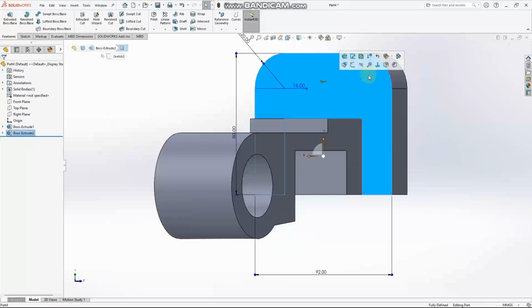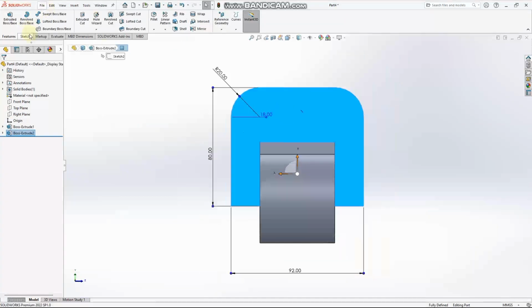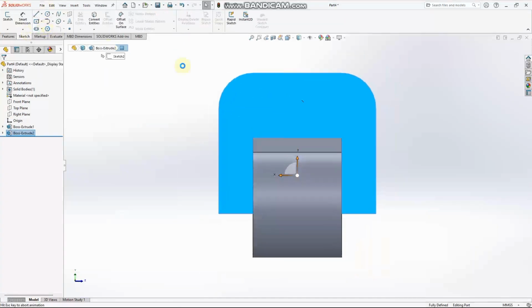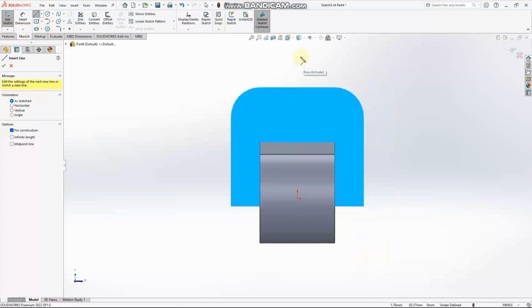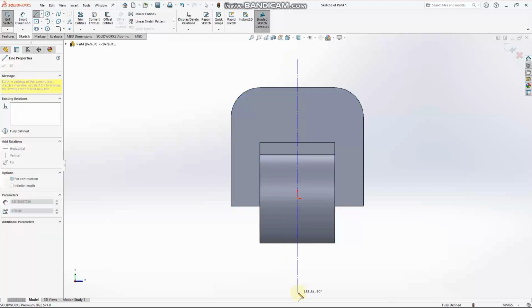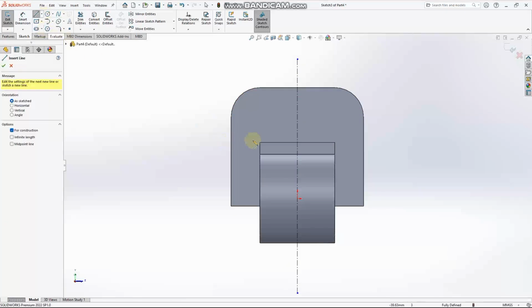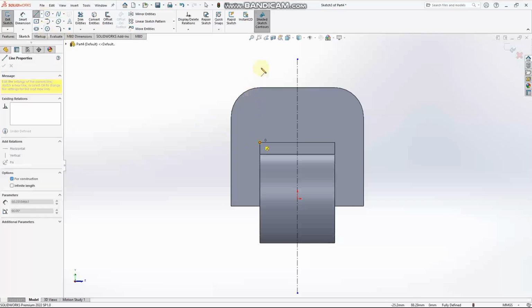We select this face in the normal tool. Go to sketch, and then we draw a center line. Make sure the center line once again is aligned with the origin. We click, drag, and click. We select the center line again. Click on this dot, and we draw a straight line. The angle should say 90 to show that it is a straight line.